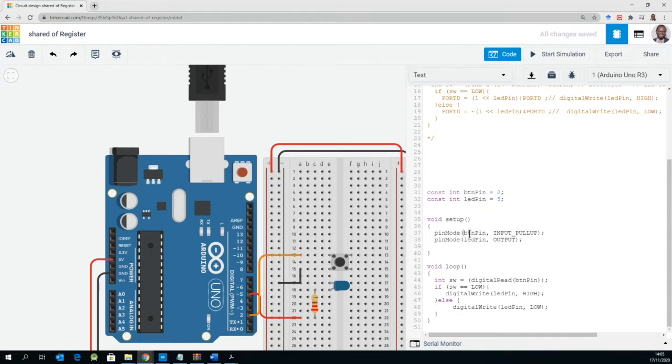Okay, so we have the push button as pin 2, and then the LED pin as pin 5. And on the push button, we really want to use it as an input pull up. Input pull up, we saw earlier that on the ATmega328P, we are able to configure a digital I/O as a pull up, or just connect to a high voltage source. And then when it gets to the coding side, we are passing the value of the push button to a variable, and then we check the state of that variable.